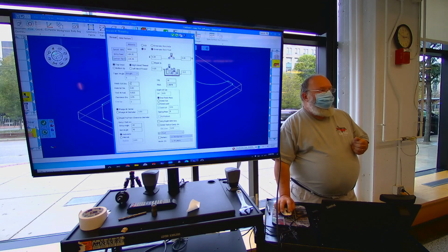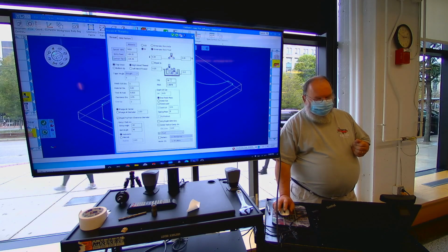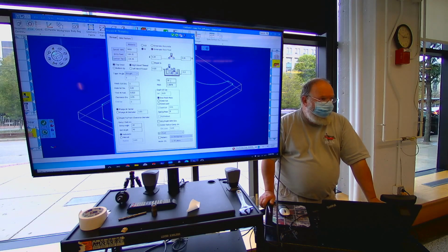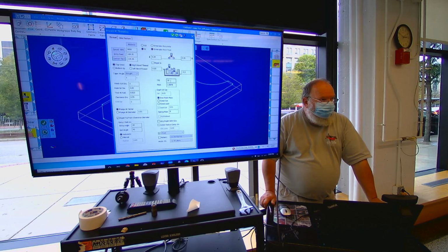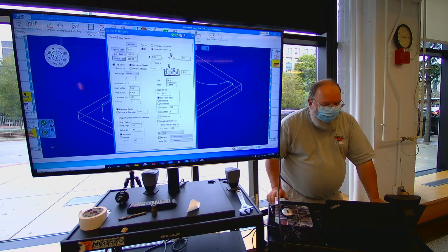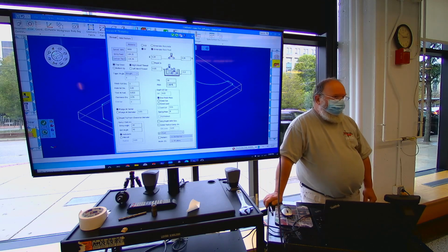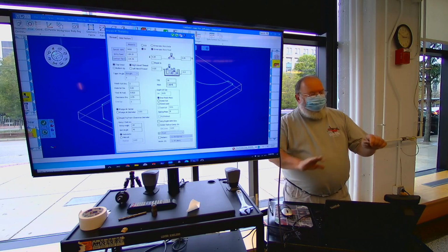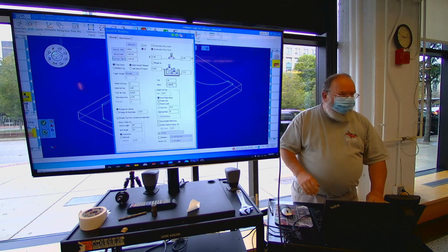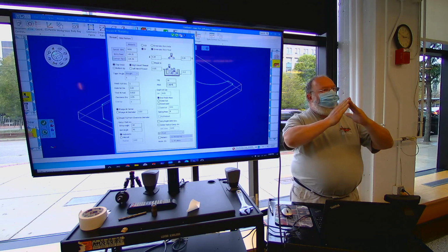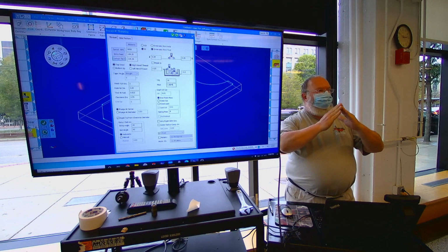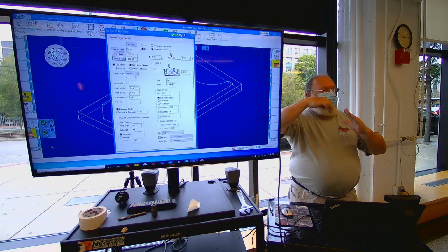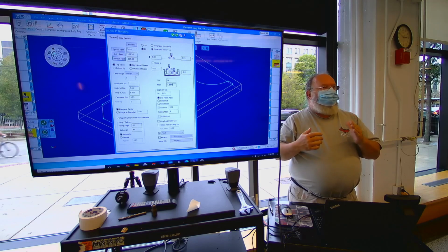I've got a 1-inch finished cut diameter, and over here I see 16 TPI. We know what that is. Threads per inch. Right underneath it, you see pitch. We know what that is. If I take this tap and I cut it lengthwise and I lay it down on the table, what I'm going to see is 60-degree triangles in succession. Okay? If I measure the crest of one triangle to the crest of the next, that's the pitch, that distance.